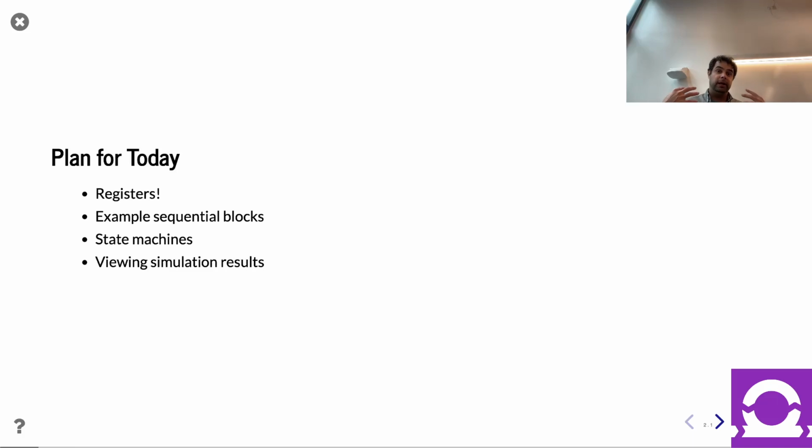In particular, when we build hardware circuits, the question is, when you spend all this time doing hardware design, what do you do with your design? Well, you can send it out to get manufactured and go through a full physical design flow and print masks and make ASICs. I'm not going to do that in this course. You could take the Verilog and pass it through an FPGA tool flow and push to an FPGA. Sure. What we actually do in this course most of the time is simulate it. With simulation, you have different ways you want to access it, whether it be looking at the output of a certain value, using a tester, or viewing waveforms. So we'll cover that at the end of today.